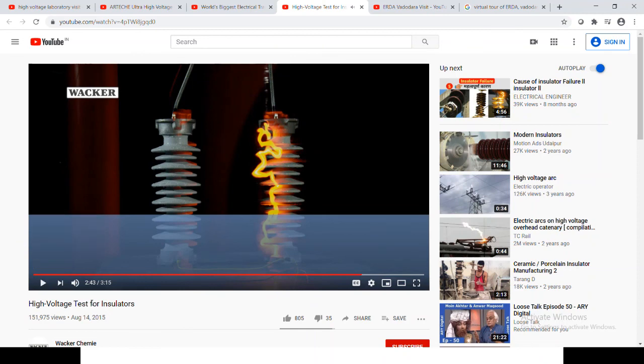So in this video you have seen the testing on the insulators with and without coating. When the coating is not applied, you have observed the flashover across the insulator's body. So the insulation engineer has modified and coated the body of the insulator and retested. You have seen the effect of that coating. The silicone coating has been done over the insulator. When there is a spray of water particles and under the impact of the high voltage stress, no flashover has been observed because of that coating.